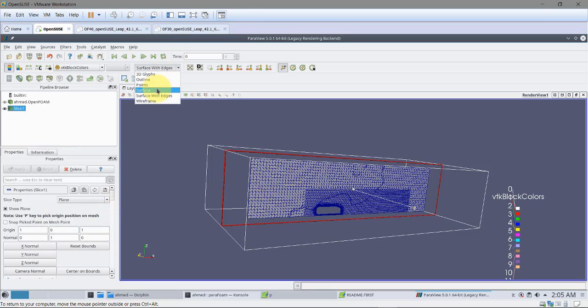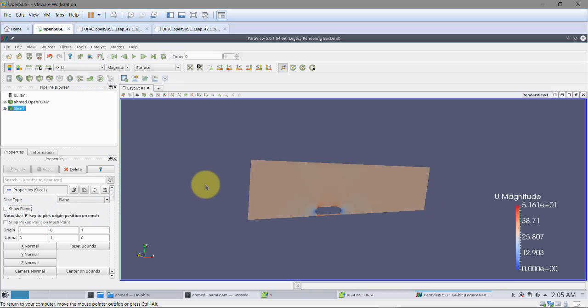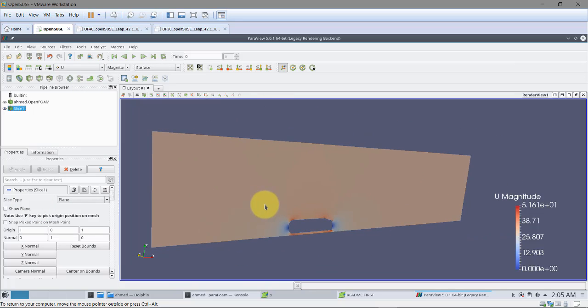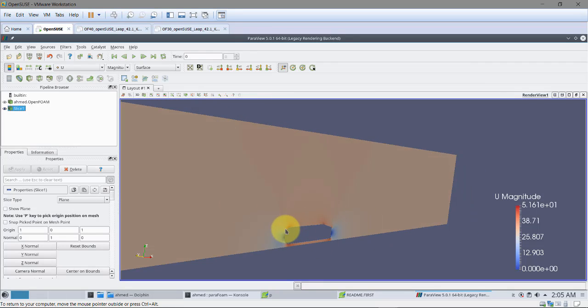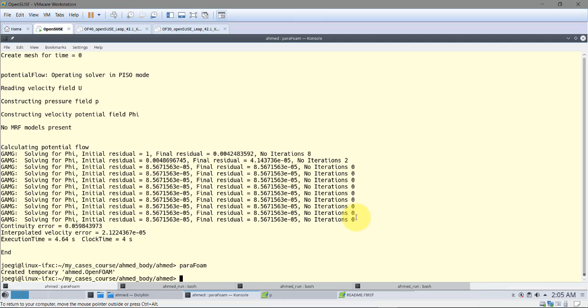So if I check here, you see that we have a velocity field, okay. And if you want, you can also compute a pressure field. You will do a projection of your velocity into your pressure by solving Bernoulli, but in this case I don't have it. I just want the velocity field, and this will be my initial condition. So we can run. As you type simpleFoam, I will save the log file using tee.